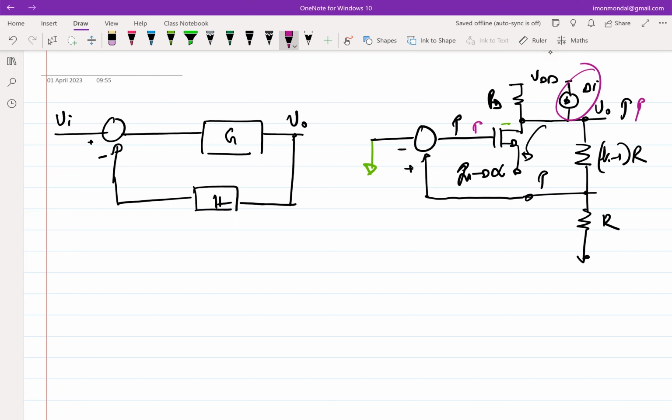No. So this delta I is not transistor current. This delta I is some external current. I am perturbing the loop separately. This is a separate current source. The question is, if it's a negative feedback and I perturb the output of the negative feedback with something, will it affect the loop? Will it affect the output? So this analysis seems to tell us that it will not.